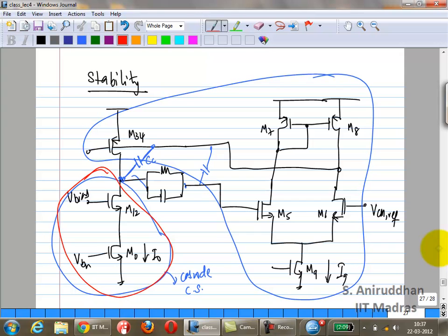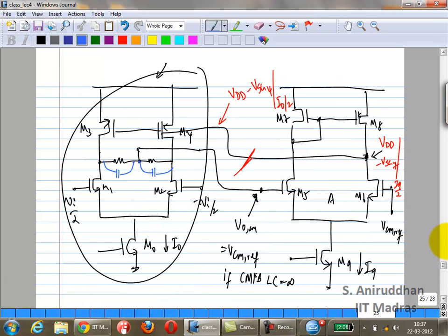In the two-stage op-amp, the most natural place to put the compensation cap was drain to gate of the second stage PMOS. Okay. Now let's say you put in a capacitance CC. So we won't discuss that anymore. You know how to do that. Okay. What does it look like in the differential picture? What is it? What does it look like here?